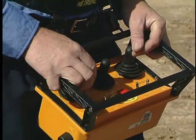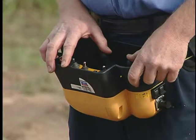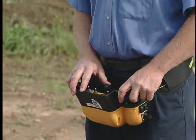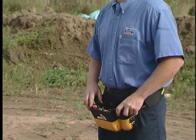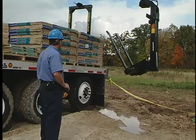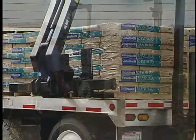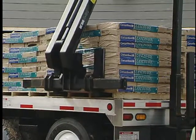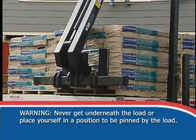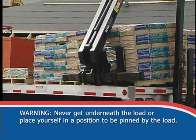Now let's review the radio remote. Radio remote control offers the operator whatever visual angle is needed. The remote gives you the freedom of movement to inspect the progress of a lift from any position. In addition, you have the best view possible for angling the fork under loads for off-lifting. Warning: never get underneath the load or place yourself in danger of being pinned by the load.